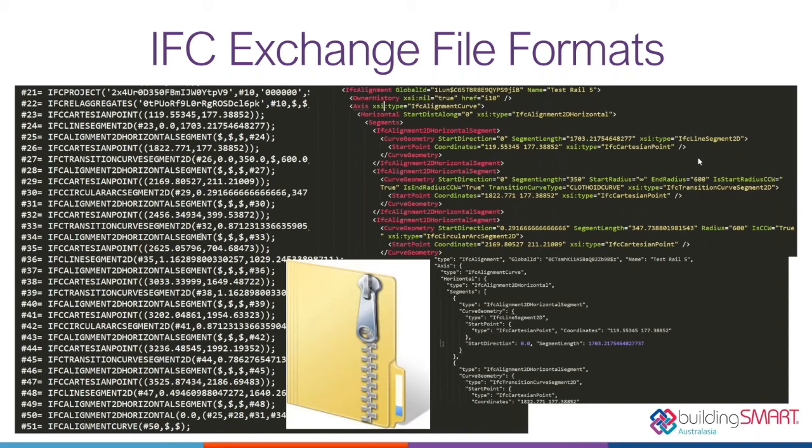Does any of the authoring software make use of IFC 4.1 with the alignment and TIN? Certainly, again, I should check. 12D does, as I recall it. So a triangulated network is added to IFC 4x.1. So certainly 12D does it. Again, I know I've done some prototyping of that with Civil 3D. But hopefully some of that stuff is coming out of the box. So we can chase that up and find more details. Ask your software vendors when it's coming or how you can access it if they've done it.